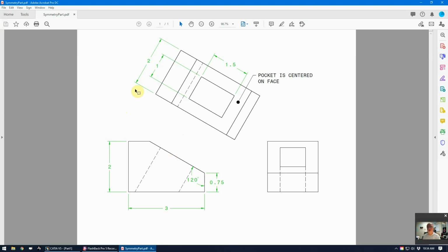Now, this presents an issue, especially when you're looking at the depth of the part. Notice this part is 2 inches in depth, and I'm expecting this 2-inch parameter to be in the model. Students might be tempted to do a mirrored extent, which would give a 1 inch and a 1 inch dimension. I'm expecting them to have the 2-inch dimension in the model, else they'll lose points.